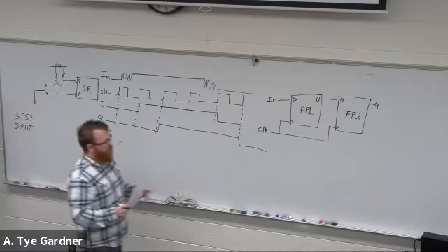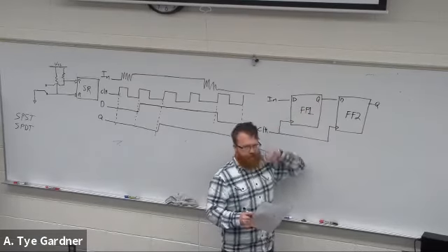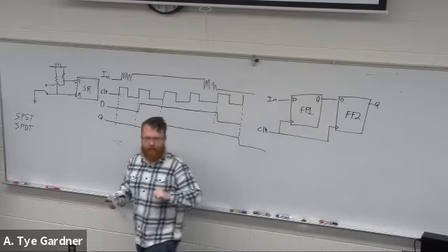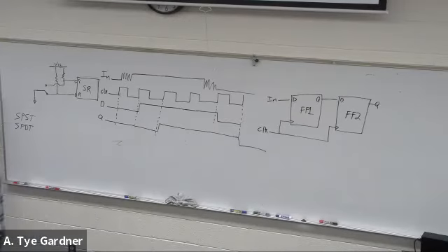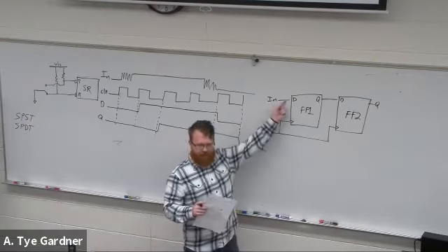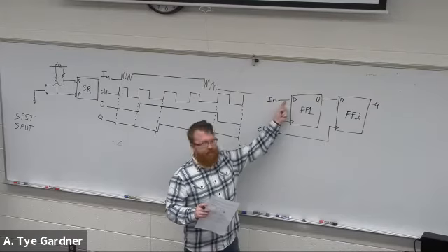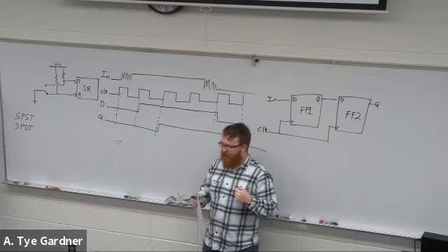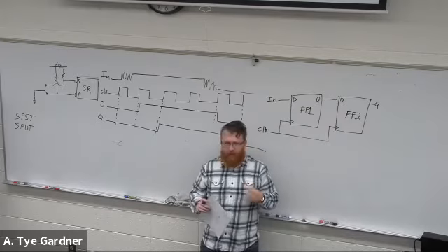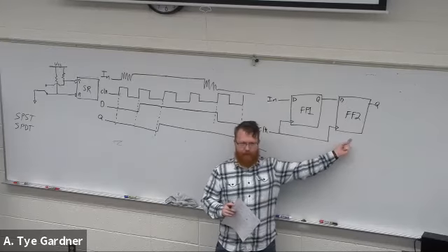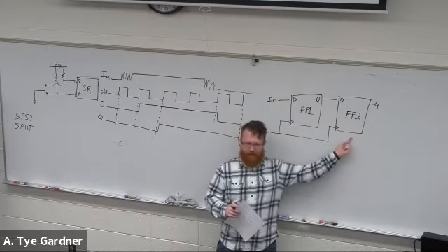In general, this is helpful because your clock-to-Q delay is generally going to be longer than your setup and hold times, and it's just the nature of the propagation delays inside the flip-flop. So this one is actually sufficient that even if this one goes into oscillations, those oscillations are highly unlikely to fall again on the rising edge of the clock. So basically what we've done is taken a very low probability and multiplied it by a very low probability, and now we have an absurdly low probability of having any issues.